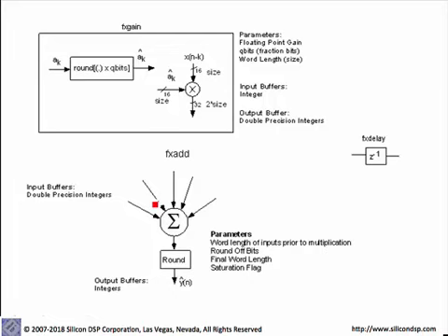And usually in a good implementation of fixed point arithmetic, we would accumulate all the results and round off the final result, and we would use 2's complement arithmetic such that you can have intermediate overflows. As long as your output is bounded, your result would be okay, and you finally round off the result to obtain a certain register size. At the output, this register size can be anywhere, like for example 40 bits or 16 bits. Typically it's the same size as the register size used for the input.